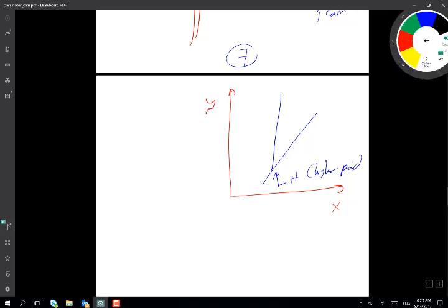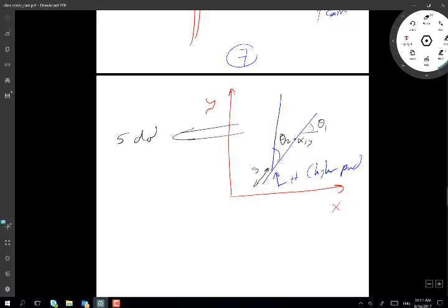It's an easy one to consider, by the way. I have X and Y of a point, and the angle, that's 3 degrees of freedom. A higher pair allows this to slide and allows this to rotate. You see what I mean? So together we have 5 degrees of freedom: x, y, theta 1, s, theta 2.